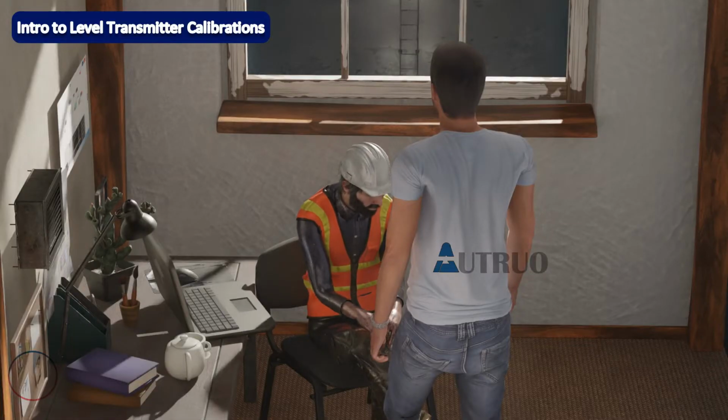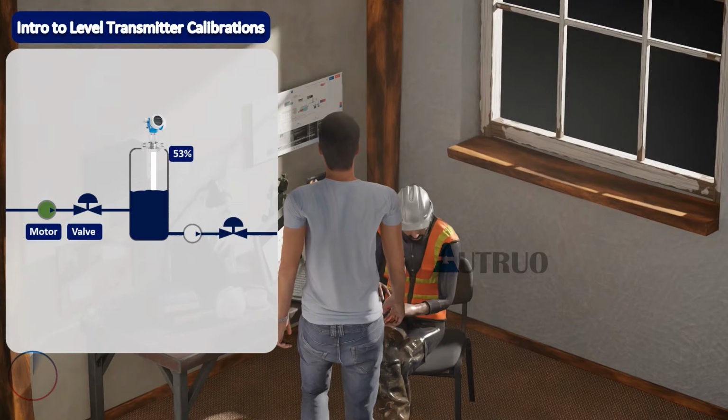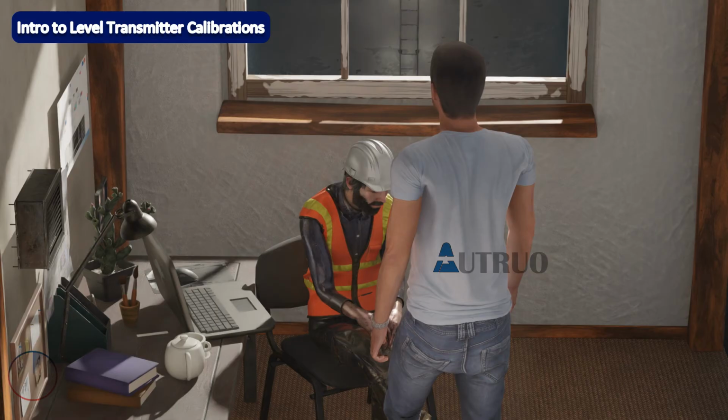Yes, I did. On the HMI the tank level is not up to 80%. The inlet valves are open and the motor is active. Okay. As long as the level is not up to 100%, the motor and the valves will be active. Are you sure you saw water drip or you're hallucinating?